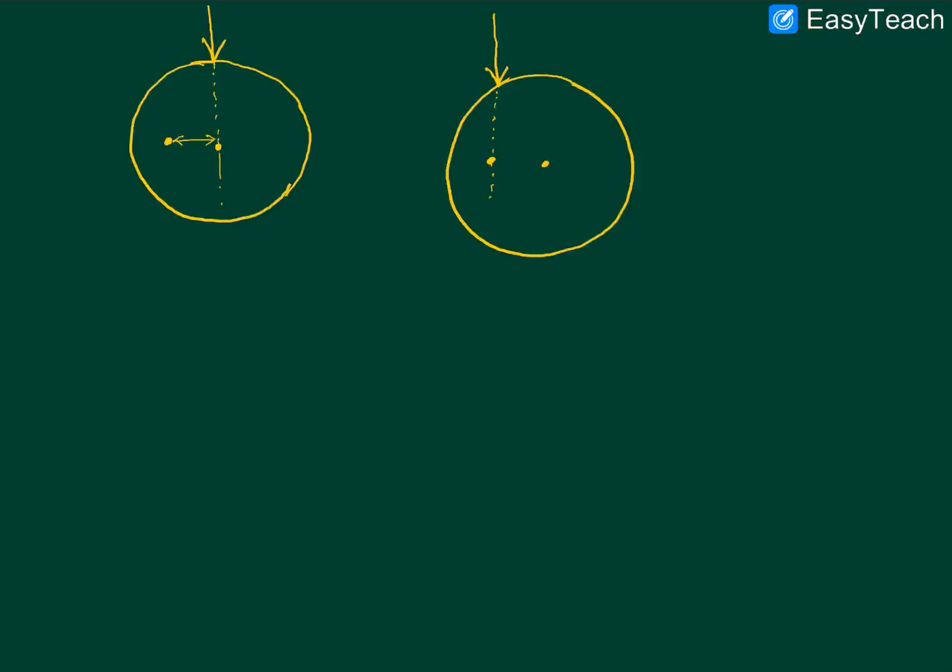So the next question which we ask ourselves is that in the previous two lectures, in the context of unsymmetrical bending, when we kept referring to pure bending, what did we mean? Well, what we meant was that we were considering the kind of applications of forces which would be inducing solely bending and no such twisting.